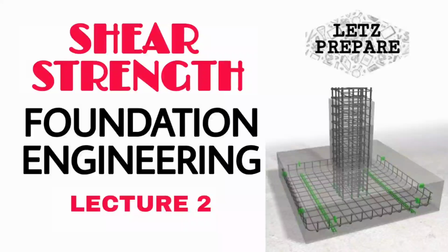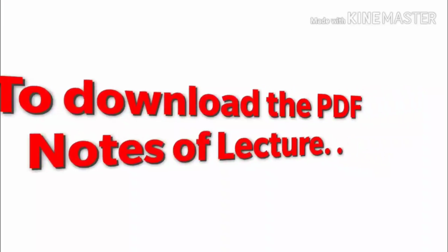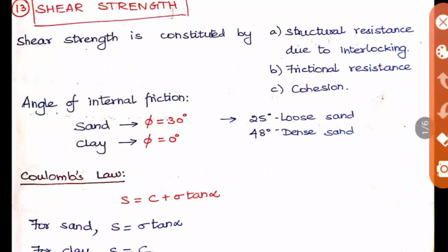Let's prepare on the shear strength of soil. Shear strength is the main character of the soil to be studied. It is constituted by these characters: the structural resistance due to interlocking of the particles, and the frictional resistance and cohesion. So these three properties only will give you the shear strength of the soil.